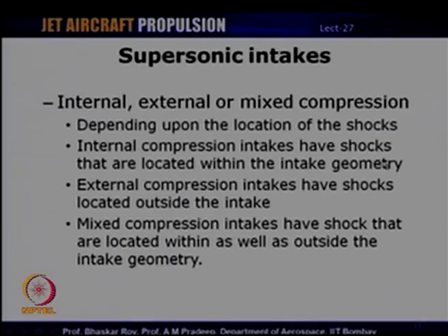That is, you have shocks which are inside the intake geometry, which cause deceleration from supersonic to subsonic, and then the subsonic diffuser which decelerates from high subsonic to low subsonic. External compression intakes have shocks which are located outside the intake geometry, and mixed compression intakes have some of the shocks located outside and some of the shocks located inside the intake geometry.